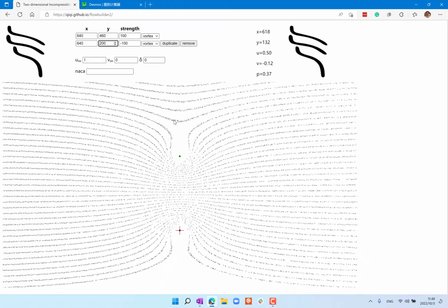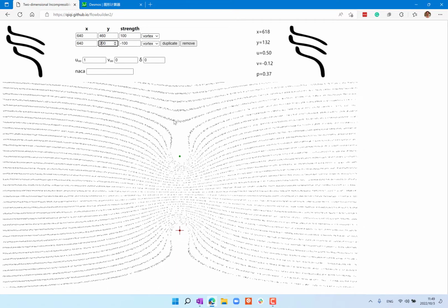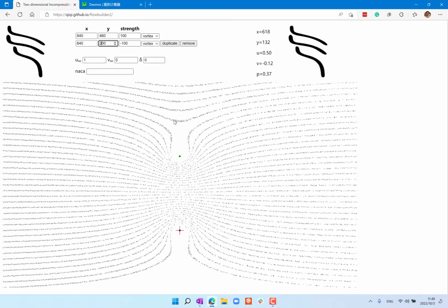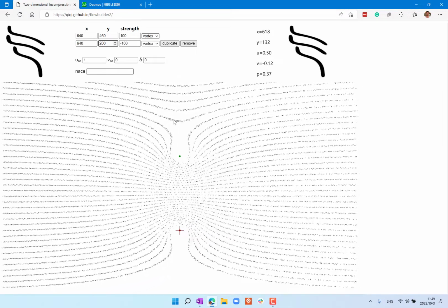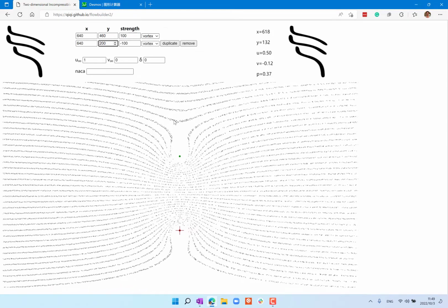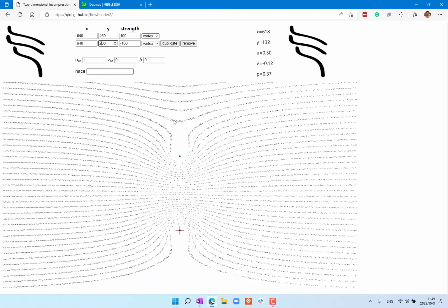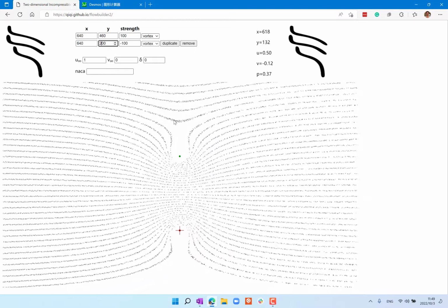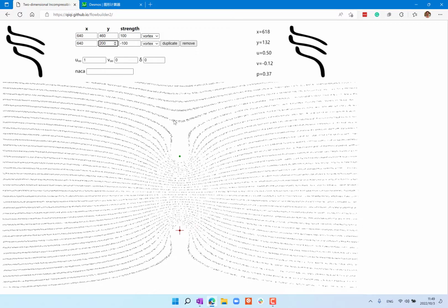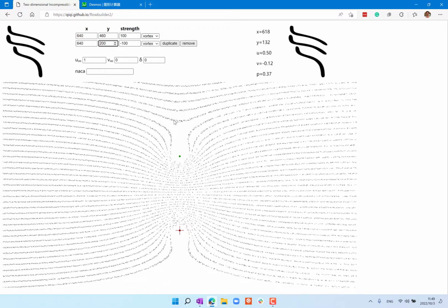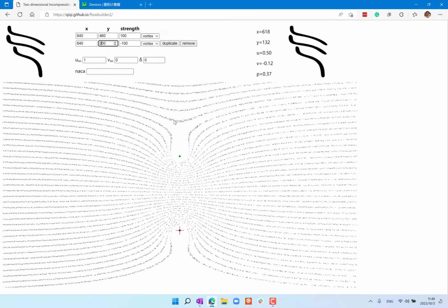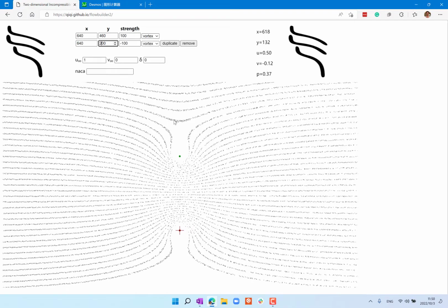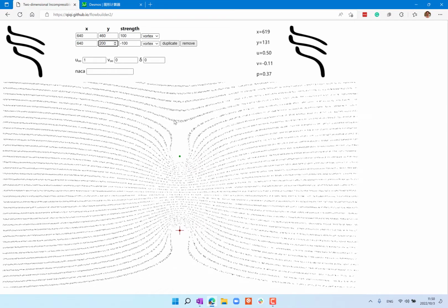Of course, you can also think physically, right? What force is accelerating? Okay, so let me ask, start from more basic. What is the flow acceleration at a point over here? Upwards, right? There is no streamwise acceleration because of the symmetry. The flow achieves its maximum velocity along the stream tube over here, so there is no horizontal acceleration. The only acceleration is the centripetal acceleration towards up.